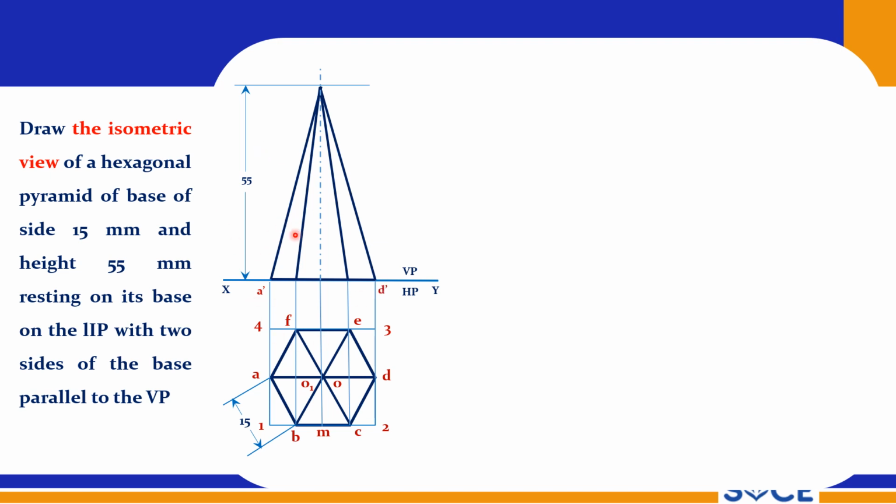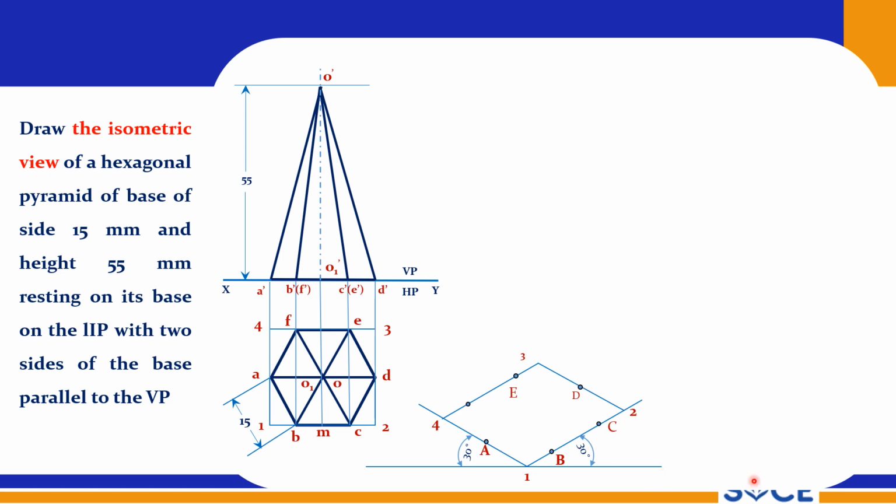So this should be drawn on my horizontal plane. So I have to draw the 30-30 plane to make it stand, right? So this pyramid is a standing pyramid, so the 30-30 plane I am using. I can make the sleeping pyramid also; I will show you that. So now this is 1 2 3 4. So I am marking A B C D on this rectangle, the iso rectangle ABCD, and mark the center, so that is my O1.